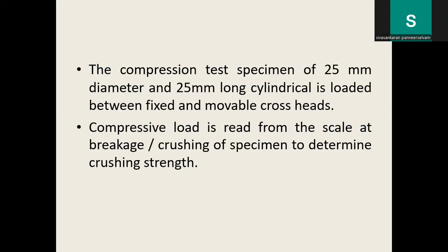So here comes the standard size of the compression test specimen. Say, 25 mm diameter if it is a cylindrical specimen, so the diameter should be 25 mm and the length also the same value, 25 mm. Consider the cylindrical specimen loaded between the two ends of the loading head.